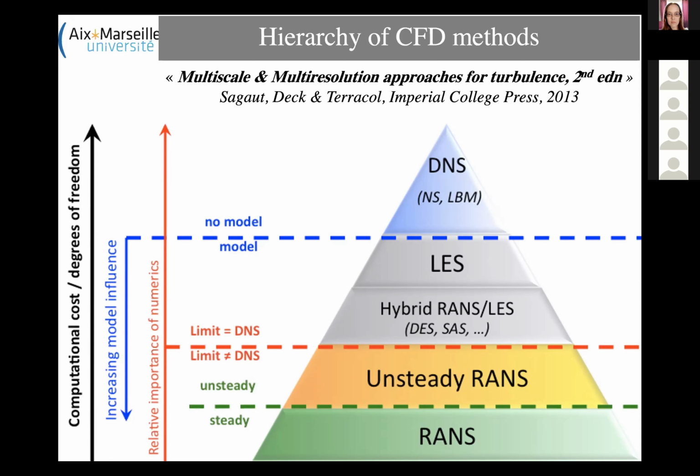Now, if you coarsen the grid, then there are some so-called hybrid RANS-LES methods in which the turbulence model is more complex, including most of the time some additional auxiliary equations. Using a more complex model, we assume that we can handle a coarser grid because the turbulence model will be able to capture more physics than the simple models used for large-eddy simulation. And of course, you can also ask for the Navier-Stokes equation. You can run some steady simulation with RANS, in which all the turbulent dynamics will be buried by the RANS model.